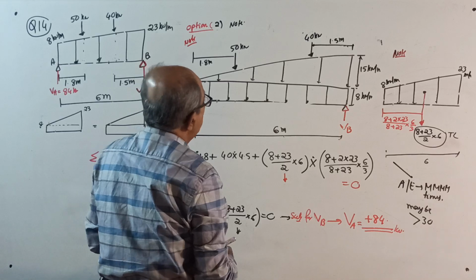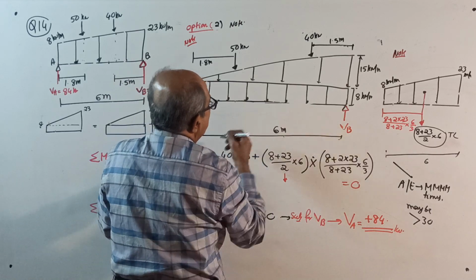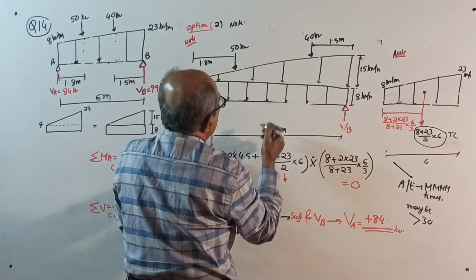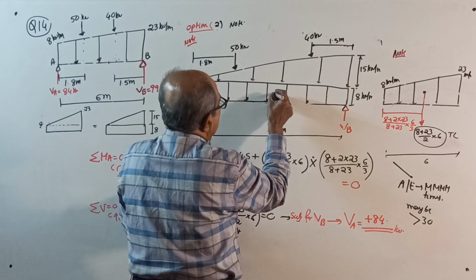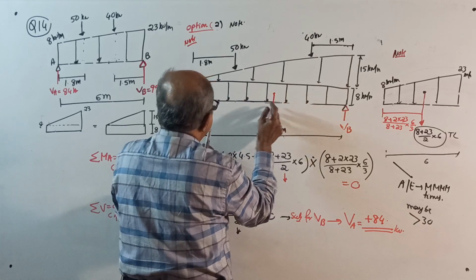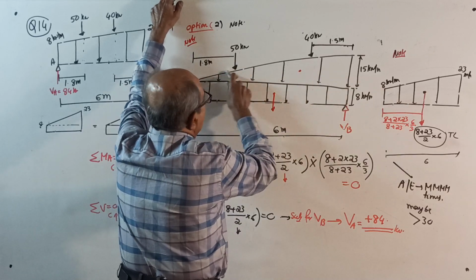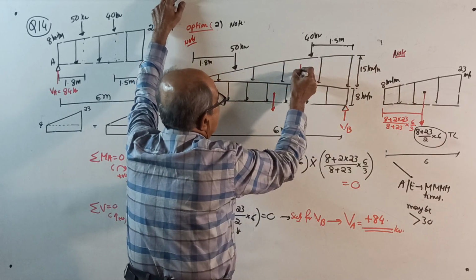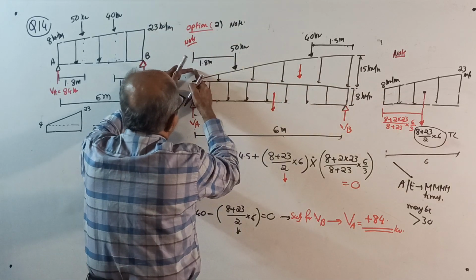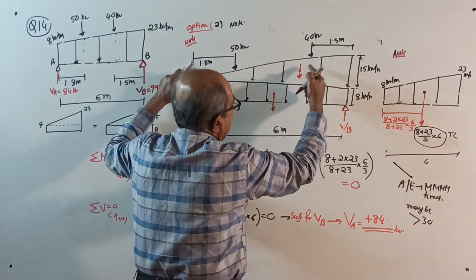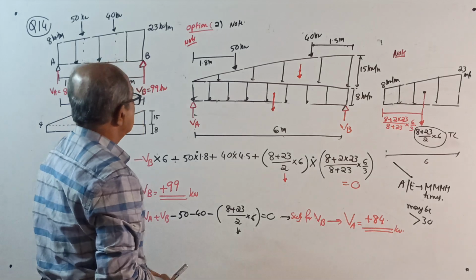Now, those who want to make a note, when you consider the rectangle, total load will be center. This is a total load, exactly center. For a triangle, total load for this triangle to centroid here. Remember, from here will be 2/3, from there 1/3. Two loads are there.